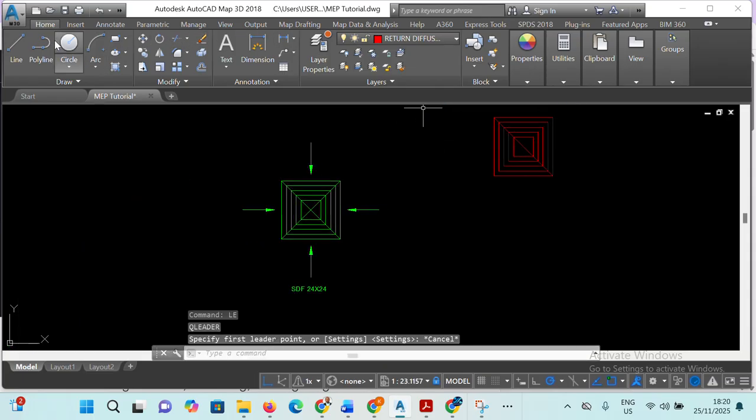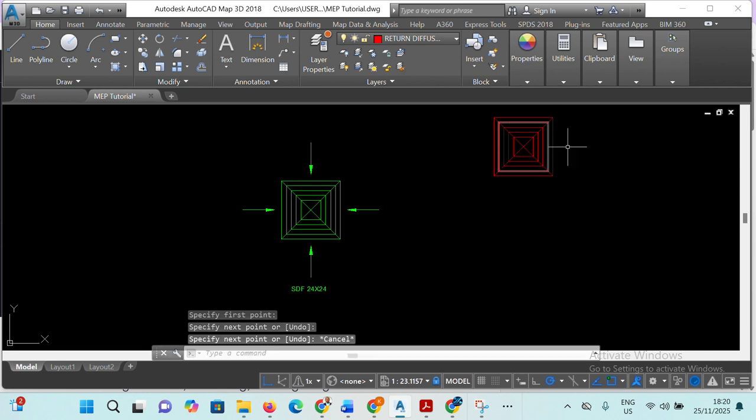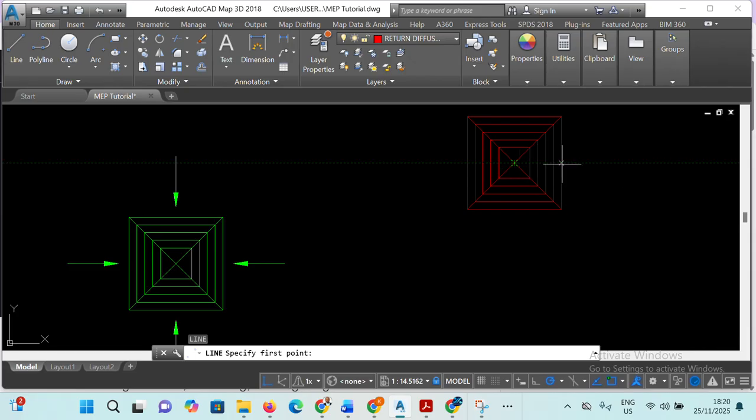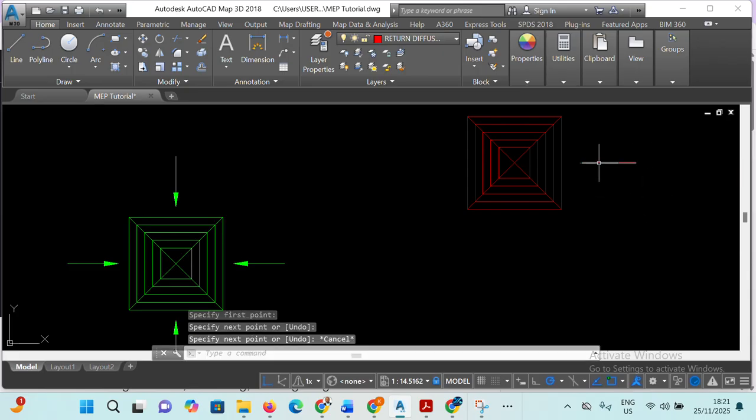To do that, we can just find the center by introducing the other diagonal and later delete it. So to get this, we'll use the LE command, draw the leader from the center. We're going to choose, so move it away from the object and there.